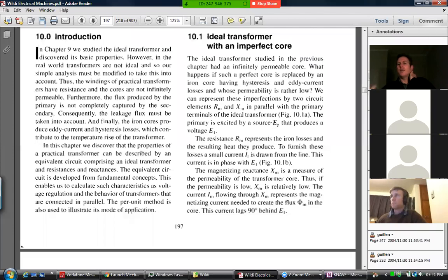Firstly, we're looking at the production of this magnetizing current. To produce that magnetizing current, you need some current because the iron is not infinitely permeable. Also, eddy currents will be produced: changing fluxes produce voltages which produce stray currents running in circles inside the metal, doing nothing but producing heat.